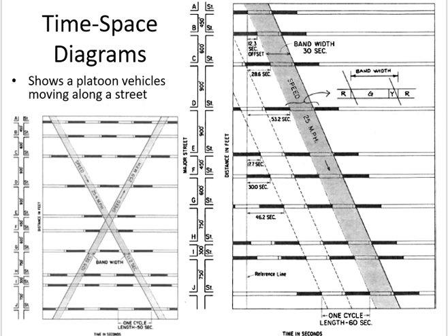What else? Now let's say you calculate an offset. Cycle length is 60 seconds, and the offset comes out to be 100. Now you will do 100 minus 60. You get 40, right? You put 40 here. You will put the green after 40 seconds. Now let's say you got 130 seconds. It's still the same. You will subtract the cycle length. So 2 cycles, it will be how much?